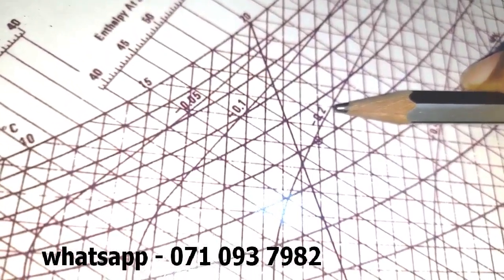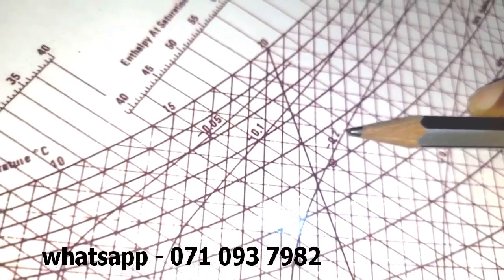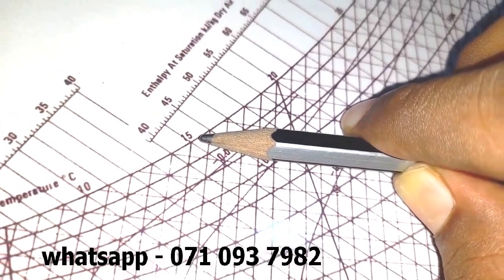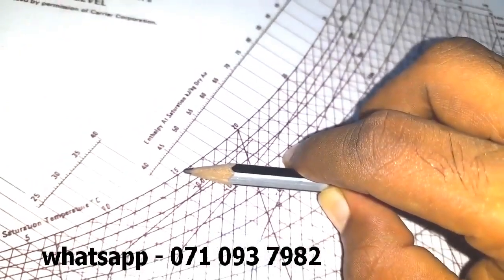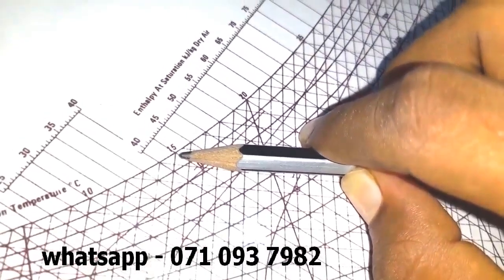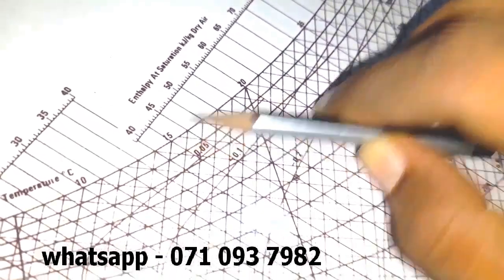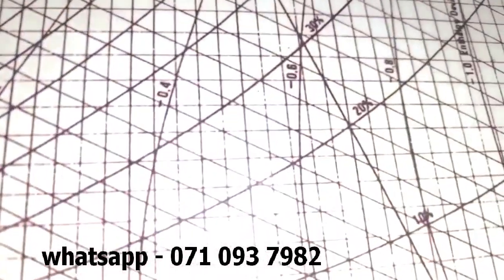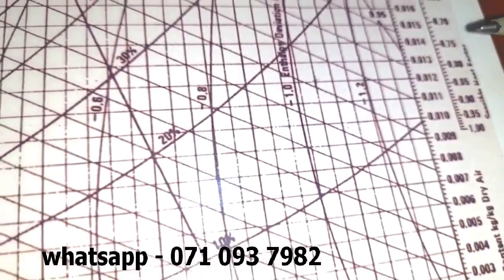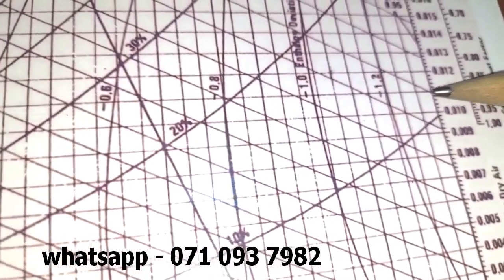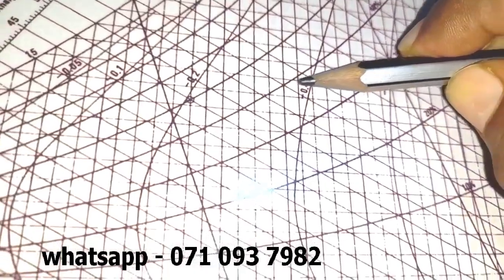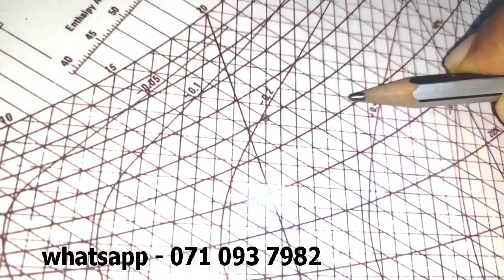This point of intersection, you project again horizontally until it touches the 100% relative humidity curve. Can you see the last curve? This one, see, this is the last curve. Okay, it's very easy to remember like that. So now let's come again. First of all, focus here, 0.011, it's here. From this line come carefully, and focus where you find 25 degrees.